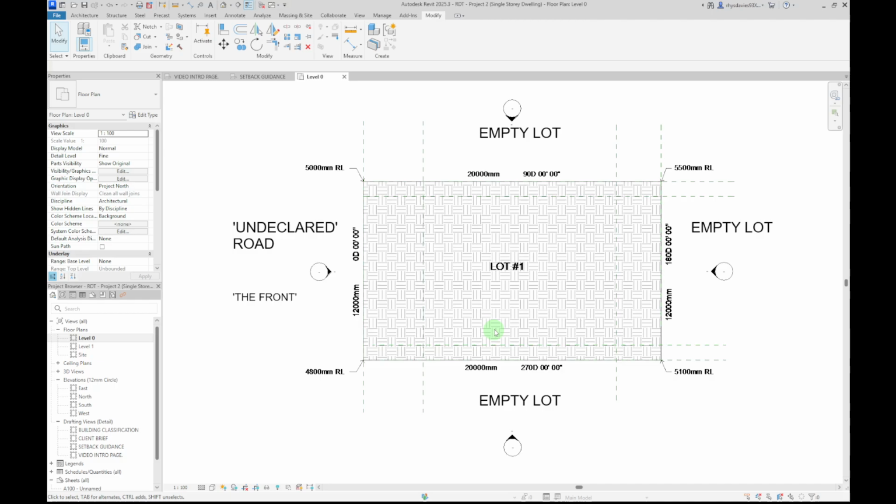And this is not about Revit, this is about building design. A really good way of looking at building design is not to try to finish the job initially. Start with very simple shapes, and look for your limitations. Find your restrictions, find out what you're really not allowed to do, and bring your project within those boundaries. So we're not going to design or draw a rectangular shape here, but at least we know that the building has to fit within that area.